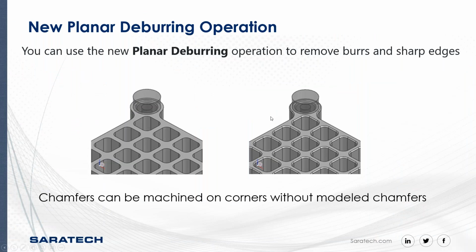They've added a new planar deburring operation, which you can run an end mill along, pretty much along the top planar lines of an object, even if they're not modeled. So this part doesn't have any modeled chamfers.